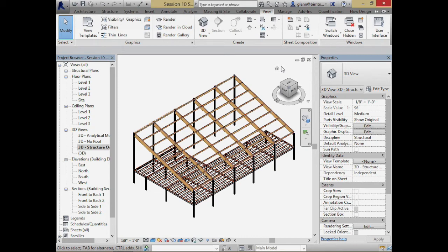A lot of buildings of any scale are designed that way, so that the frame is quite independent of the facade. And by doing that, you have a lot of independence. The facade can change very radically, and it won't have any impact on the structural stability. So it's very common to separate those things and think about the facade as being the skin that just sort of supports things. Sort of like our human body, our skin's not really supporting very much. It's keeping everything inside, but it's just a skin on the outside. That's a very typical approach.